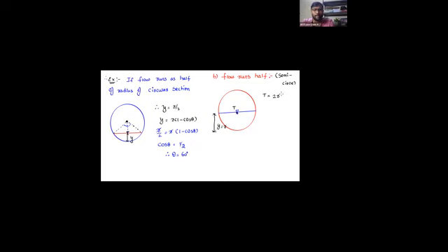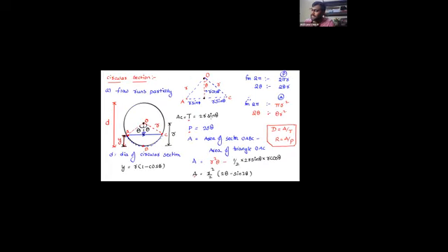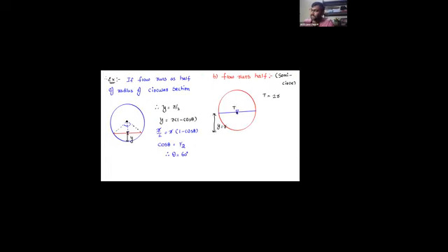So 2 theta is going to be 180. Then what is theta? 90 degrees, right? Theta is equal to 90 degrees, and if you substitute, sine 90 is equal to 1. Or simply, as you know, flow runs half, so the top width is going to be 2r. And what about the wetted perimeter, please? Total circle 2 pi r, and for the semicircle, pi r.